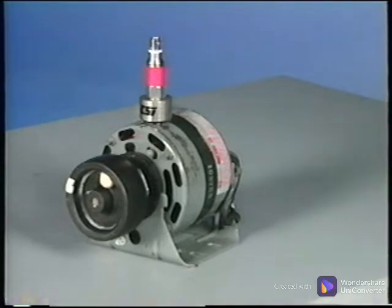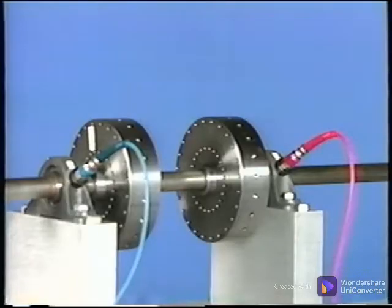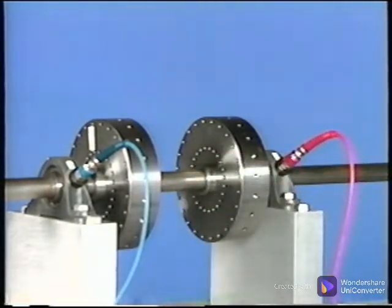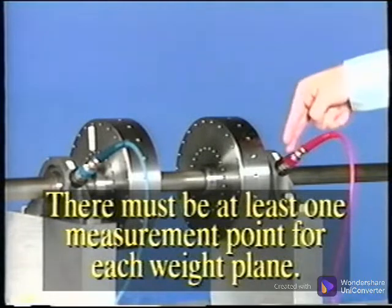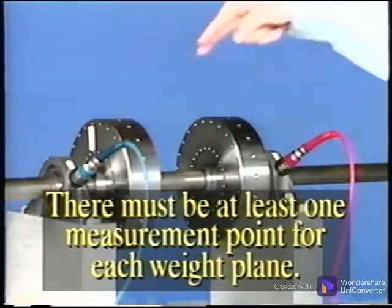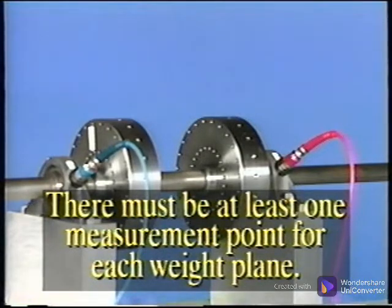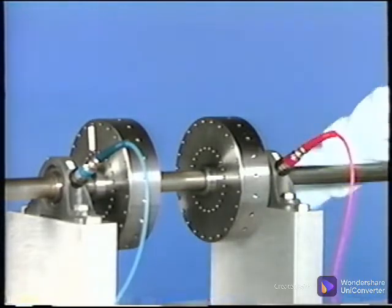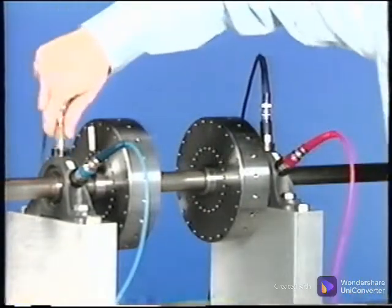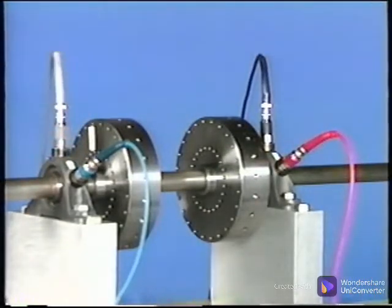This rotor kit has one weight plane where balance weights can be added or removed. But this rotor kit has 2 weight planes where balance weights can be added or removed. So by its very nature, it has the possibility of being more complex. There must be at least one measurement point corresponding to each weight plane in order to make the calculations for correction weights. But you may want to make more than one measurement point for each weight plane to ensure that lowering the vibration in one direction does not raise it in another.